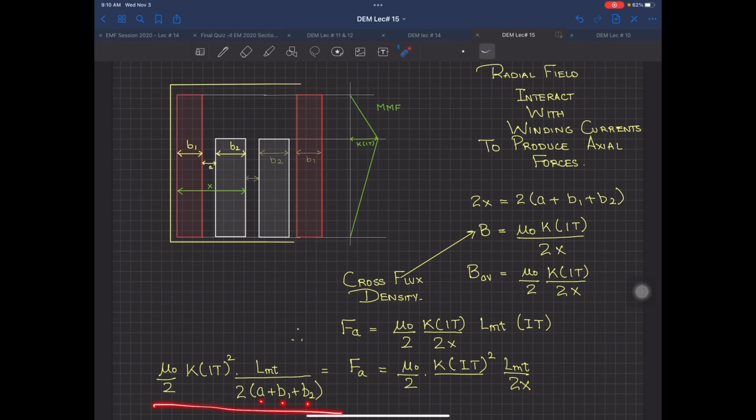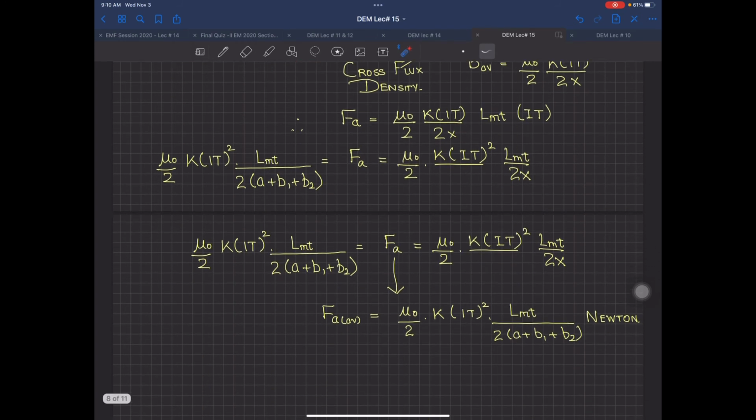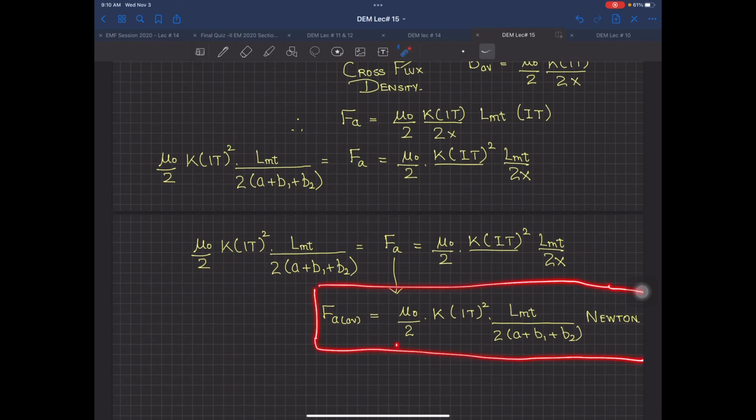So you now have axial forces for unsymmetrical winding, which means there is a distance that is not covered. So the windings are uncovered, and based on this, this is your average value. I have how this average value is done based on the same assumption. If the current is RMS, you square it, the RMS value is still I square. Okay, average value, same assumption over there, this is your average value. Now in this one, you can see very easily that this factor is additional.